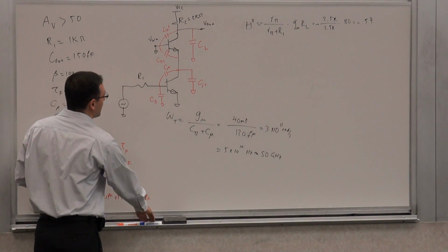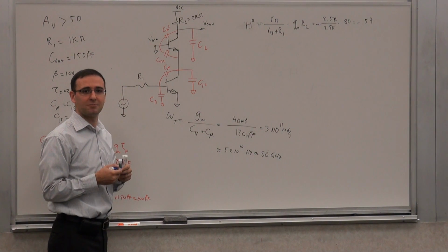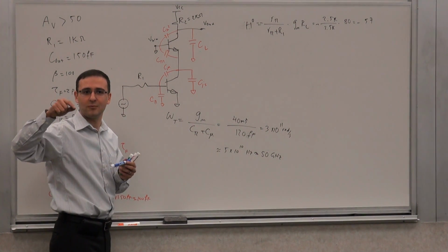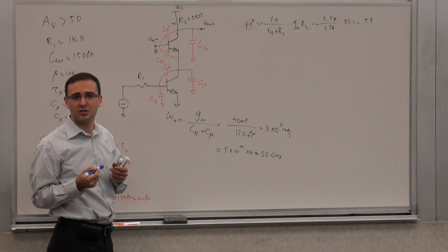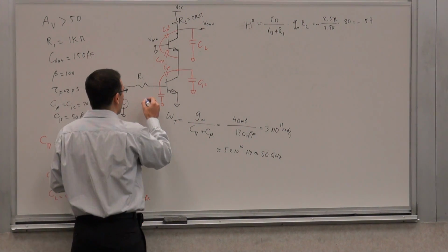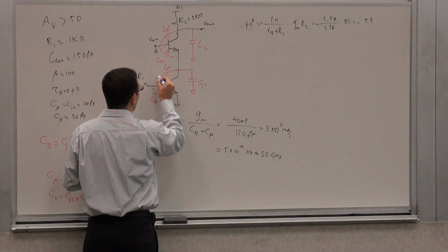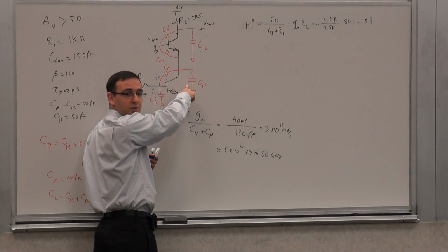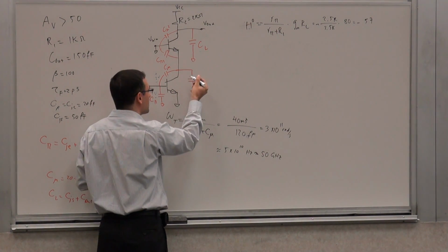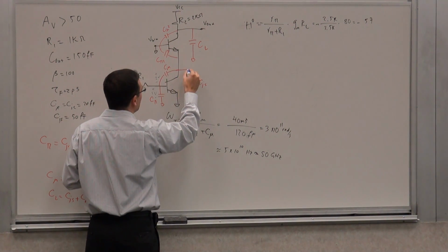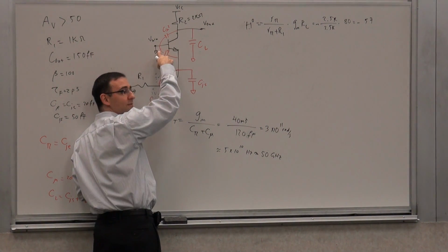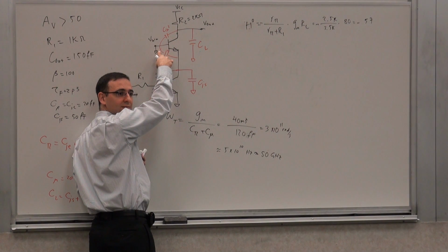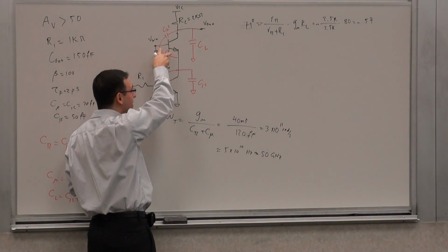So one way, the brute force way of doing it, is basically just looking at the capacitors and putting initial conditions and seeing if it works out, right? So let's say 1 volt here, 2 volts here. This is not well defined, right? I mean, this is already defined. I know what the voltage across this capacitor is. This is 3 volts, it's defined. So I have 2 already. And then I've also defined the voltage across this guy, because this is from here to ground.